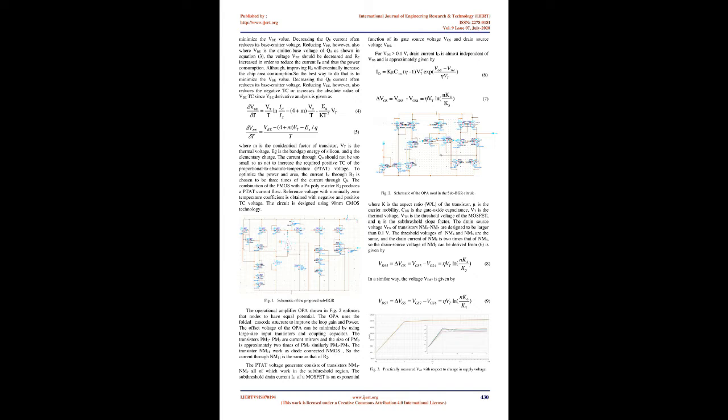2. Proposed voltage reference. Fig. 1 shows the proposed sub-BGR circuit using a single parasitic vertical PNP BJT, i.e., Q0, to generate the CTAT voltage and poly-resistor R2 for PTAT voltage generation. The circuit operation can be described as the summation of two currents, one PTAT and the other CTAT. The BJT emitter-base forward voltage indicates a negative TC.